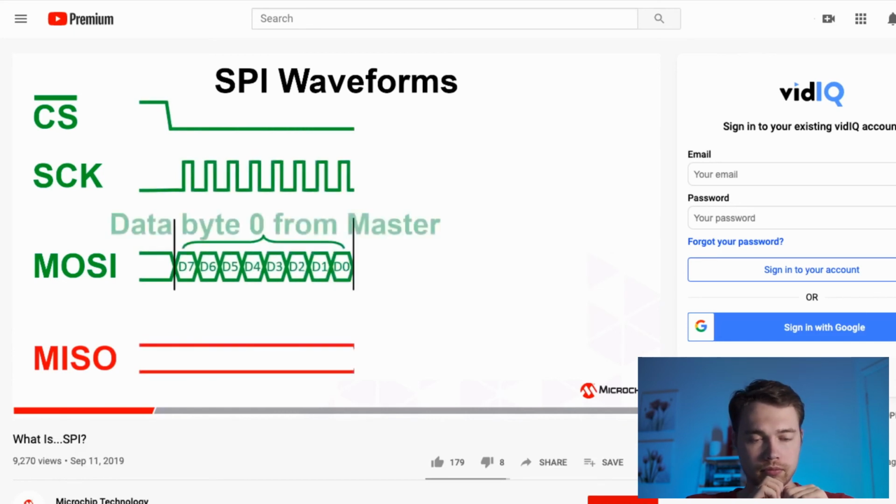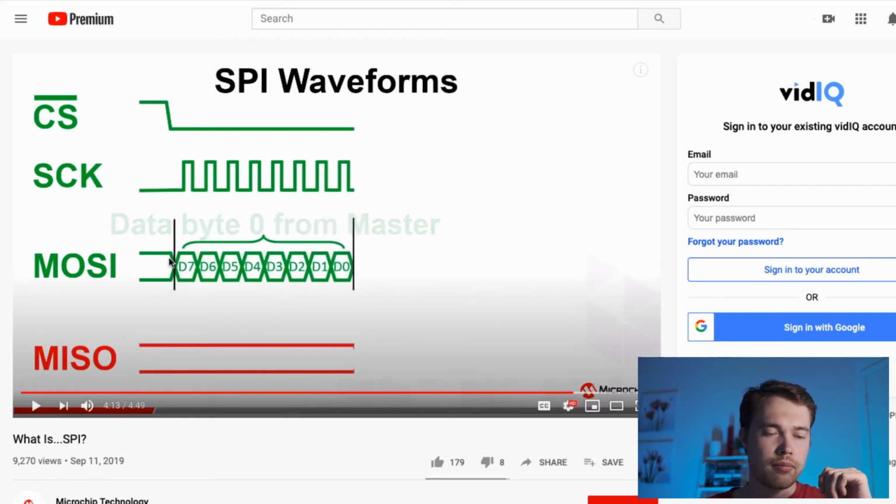After CS has been driven low, the master then generates clocks on SCK to shift command and/or data bytes into the slave using the MOSI signal. This can probably look confusing, right? It's not 0, it's not 1, so what is that? That basically means you send in either 0 or 1. It's a weird way of showing that, just a snake like this. You can go either to the bottom or to the upper portion, or you can change in between all the time.